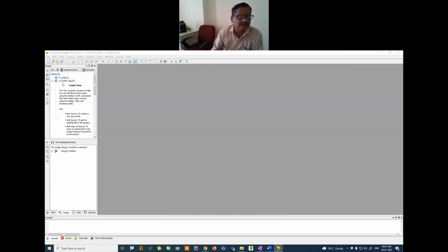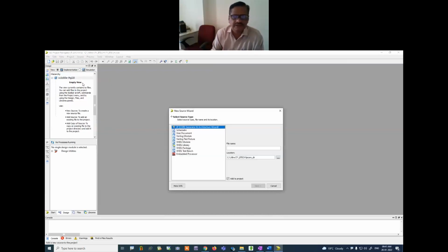Now, click on this device, not on the project. This is your project. Click on the device. And after clicking on the device, right click here and then select new source. Right click and new source. Then in this case, we will select the VHDL module option, and give some name to that module.